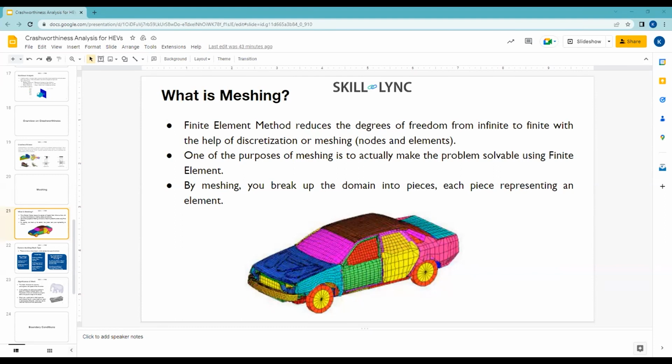Now YA by L, you can understand that F equals kx, so you can put that over here. Where x was your displacement, or in terms of your elements, you can call it a deformation. So you put that as x. Now this becomes your stiffness. That stiffness was there when you fix this one node and apply an external force at the other node. So that stiffness matrix was there only then.